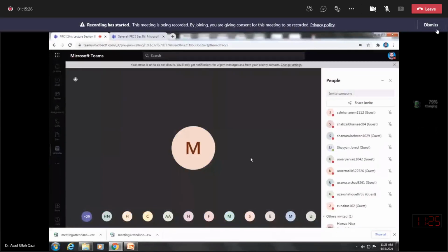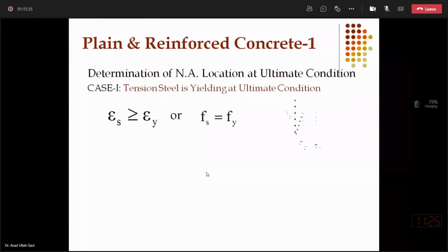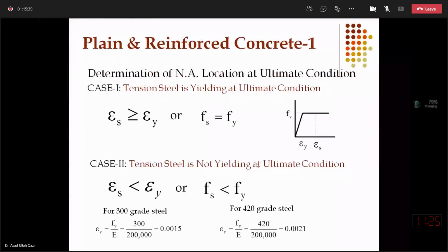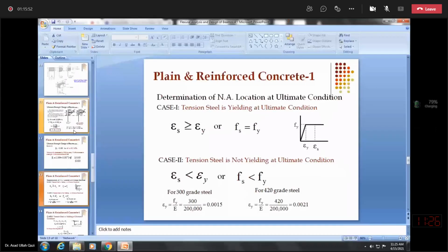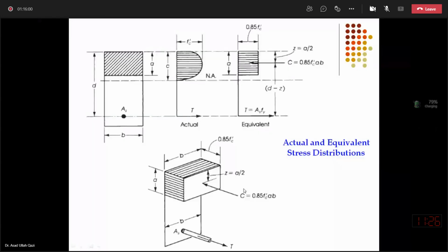Now the slides. This slide is very important because up till now we have been talking about the section behavior, and in section behavior I only focused at the moment on getting C and T. Furthermore, we said that in terms of strain, the crushing and ultimate strength in the top fiber will approach softening, and this is the failure limit, that the topmost fiber will approach 0.003.